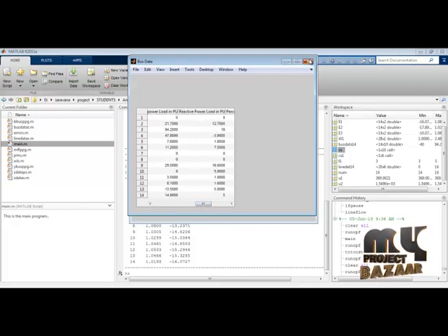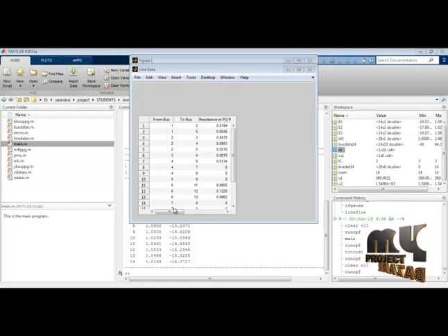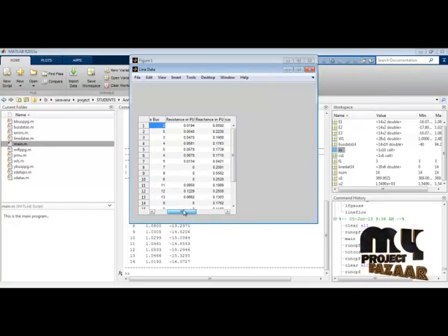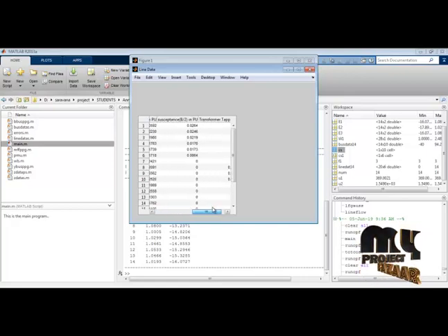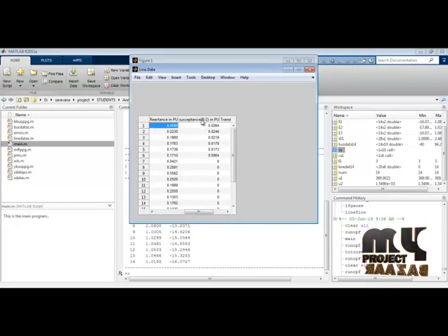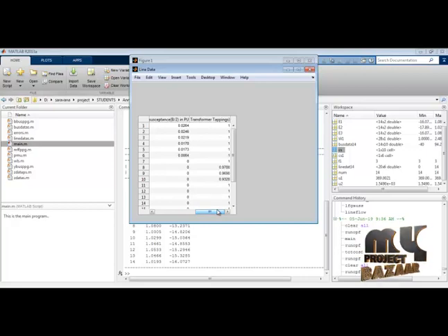Another thing we can see is the line data. This is one line data, from and to: from bus and to bus, which bus connects to which through the lines. So we can go from bus number 1 to bus 2, and so we can identify our lines. For these lines, we can find out how much resistance, reactance and susceptance there is. Susceptance we can find from the resistance and reactance, so we can calculate susceptance values and the transformer ratios.